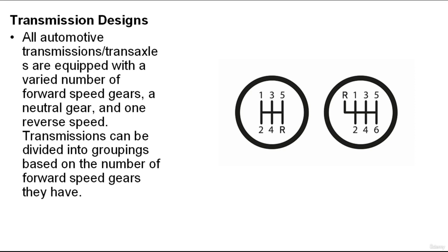Overdrive gear reduces engine speed at a given vehicle speed, which increases top speed, improves fuel economy, and lowers engine noise. Most late model 5-speed units incorporate fifth gear in their main assemblies. This is also true for the 6-speed transmissions and the transaxles. The fifth and sixth gears are included in the main assembly and typically provide two overdrive gears.